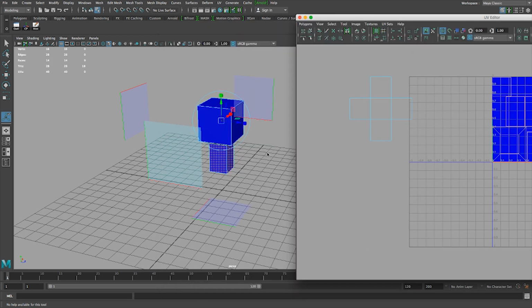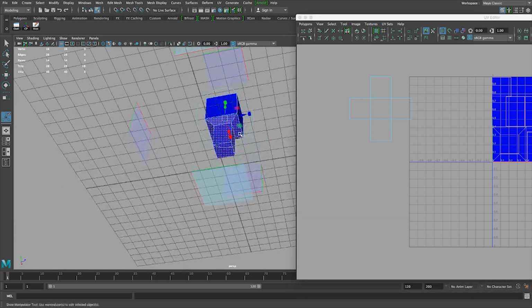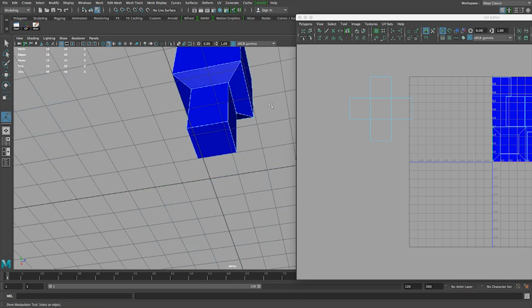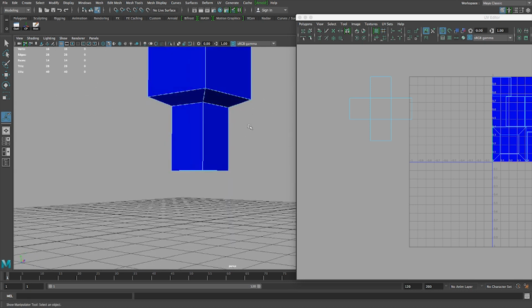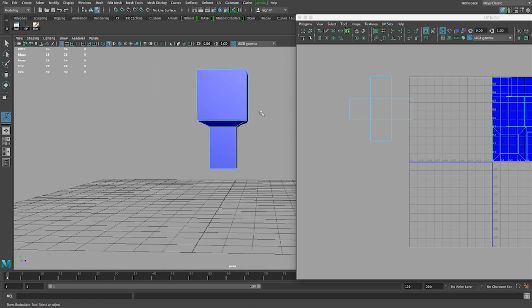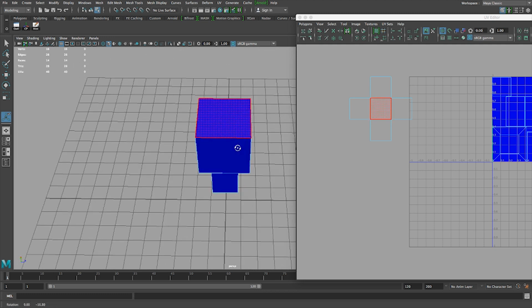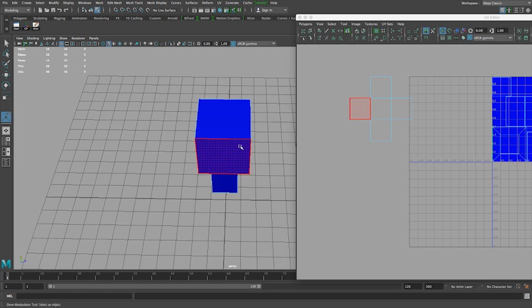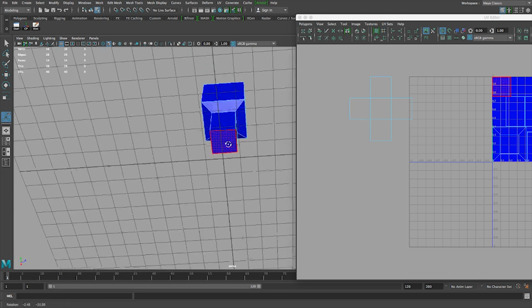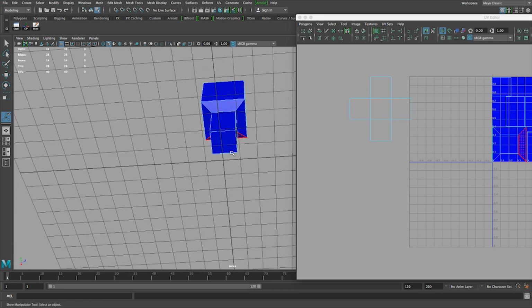Okay. We need to now think, how do we connect these two to have a smooth map for everything? I want to have a map that goes, I could do like I did before, and connect. And if you see this square here with triangles, this is this part. Wait, I'll click outside so we don't see these projections anymore. So I have this as UV'd, it's like a plus. Basically we have this one, and I open them up like a flower on top of it. Yeah. Now I can do the same thing and start from the bottom here and connect everything.